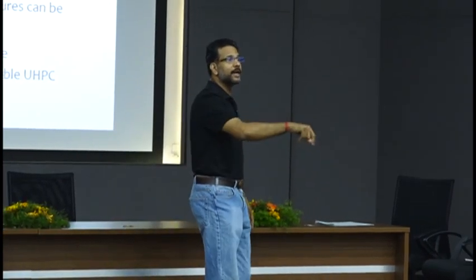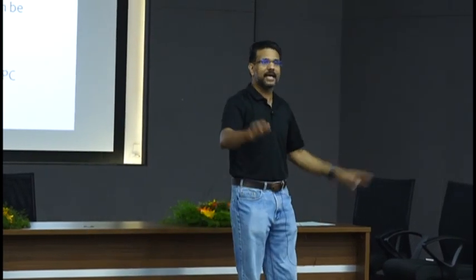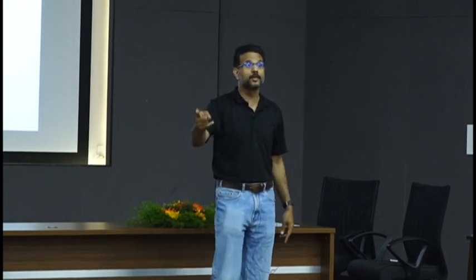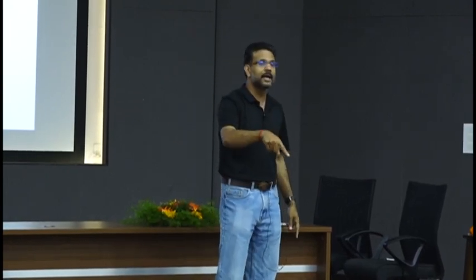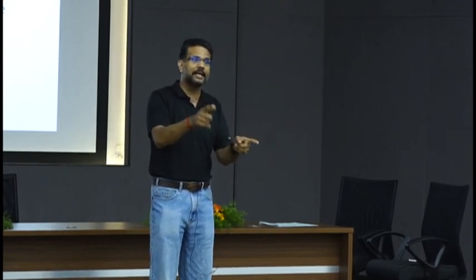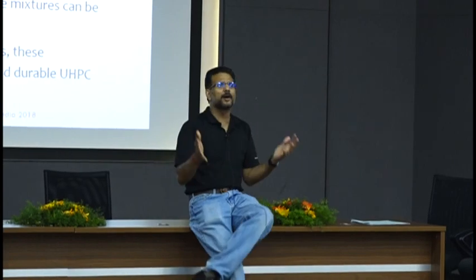Now, you throw some sodium hydroxide in the system like you do for alkali activation. Your calcium hydroxide will say thank you very much, it will sit there, and fly ash also will sit there. Fly ash and calcium hydroxide will not even show that they know each other. They will not do anything because sodium is now more powerful than calcium as a cation, and sodium will say, I'll do my job, you guys keep going. If you have a cement with a higher alkali content, that's exactly how it's going to happen. So if you have 1 or 1.2% sodium oxide in your cement and you're expecting your fly ash to do your conversion, you will not get the conversion that you need. So there's a lot of complicated stuff.